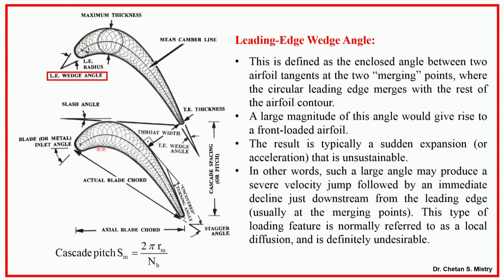Okay. Now, here if you consider I will be having more acceleration, that will be happening. If I say my wedge angle to be lower, what will happen? I will be having my acceleration up to certain limit. So, now the situation is on the blade surface, my acceleration that will be attained up to certain limit, then I will be having my transition flow, and later on I will be having my turbulent flow. And under turbulent flow, after some distance, as we have discussed, there may be chances for the flow to get separated.